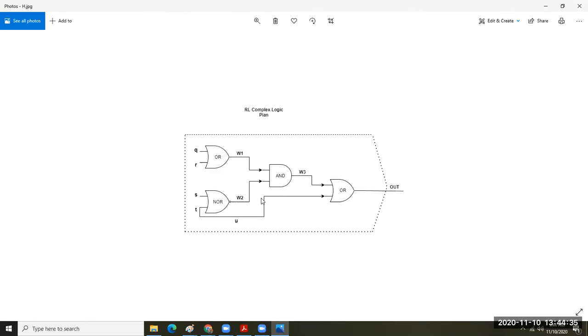So, all right. The only thing I would offer in terms of constructive criticism is that you need to do something with the T input down here in the lower part of NOR. Because by looping the two inputs here and there, that's going to get wonky. I mean, when you run your HDL, if you left it like this, it would throw a red line at you. You'd have some kind of error.